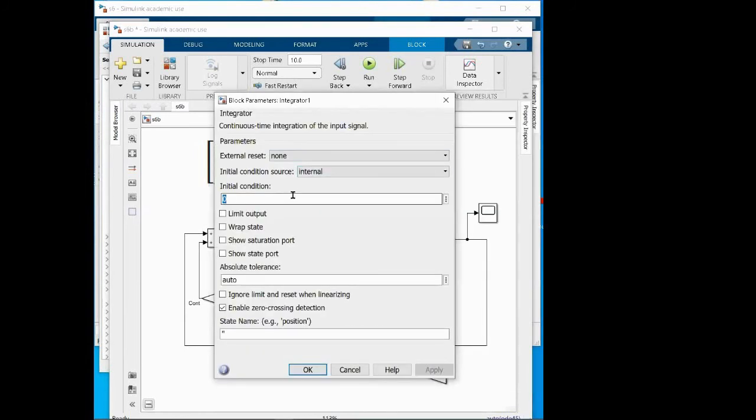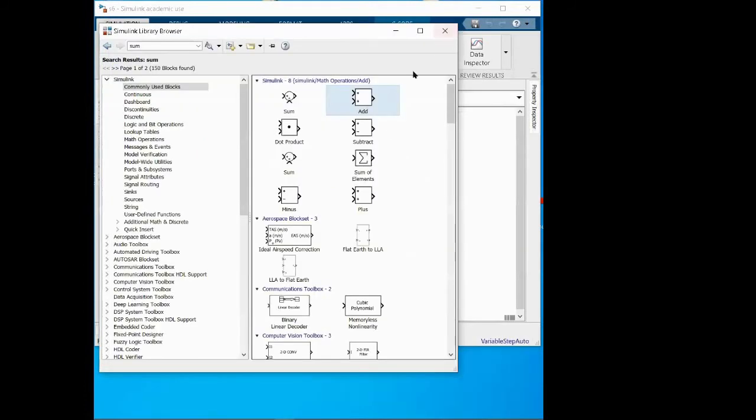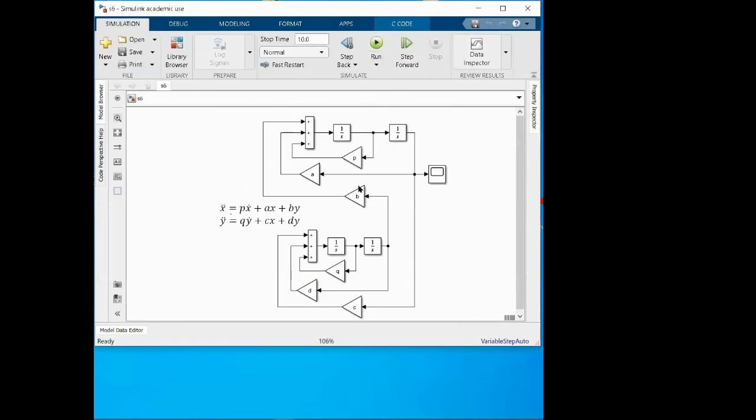Let's take any condition. Is there a way to separate the initial conditions for y and x, so you can have a velocity or position of 1 on one of them and 0 on the other? In this matrix way, no, they are both together, because now each line consists of a vector of 2 variables. If you need to set separate initial conditions for velocity and for displacement, the preferable way is to work with this way of modeling.